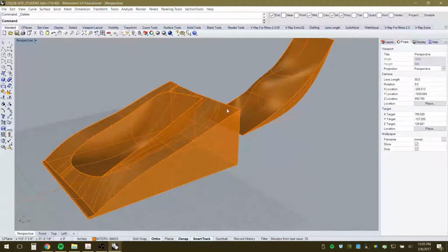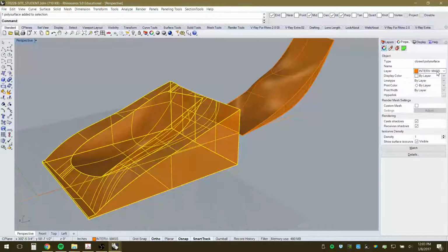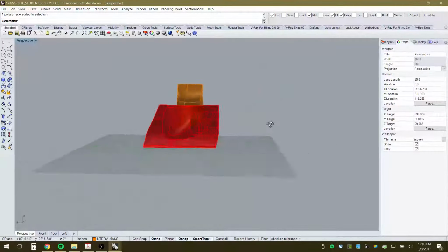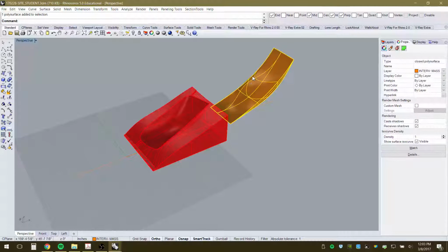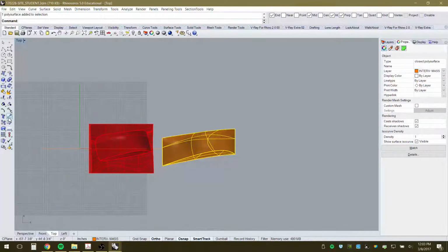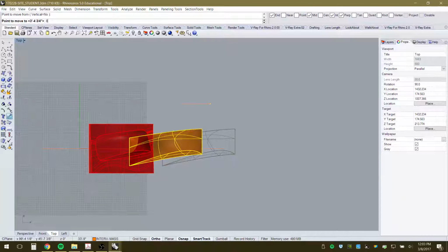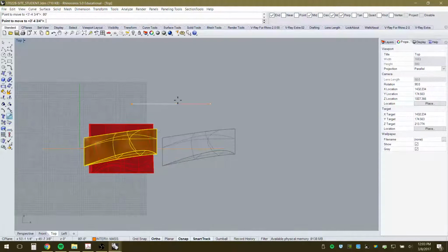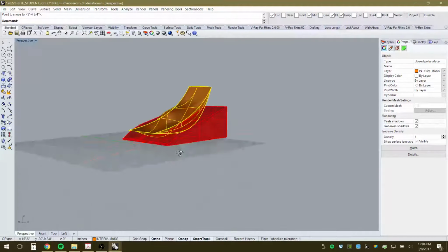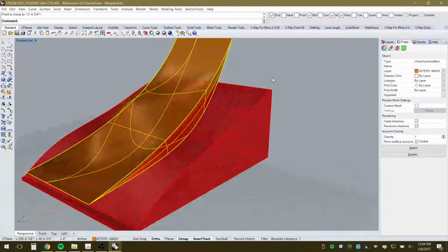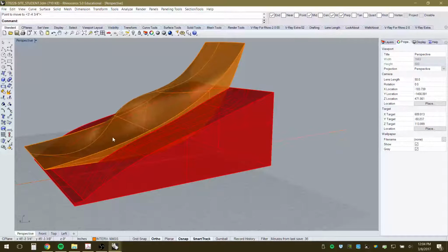Alright, this is on the wrong layer. Sometimes when you Boolean, it's going to change the layer, but I'm going to put it back on the site topo, so it's red. And I'm going to bring this, the actual intervention back over. So I'll go in my top view, move, and I can type in my 80 feet, and then it's exactly where it needs to go, and I'll set the left click to enter that. Okay, that's looking better.